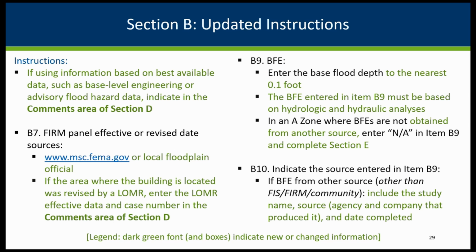So all sections have updated instructions. For section B, be aware that if using information based on best available data, such as base level engineering or advisory flood hazard data, you must indicate that you're doing that in the comments area of section D. So I think as far as base level engineering, for example, that would be if you're obtaining a base flood elevation using our Lake and Flood Elevation Online tool.